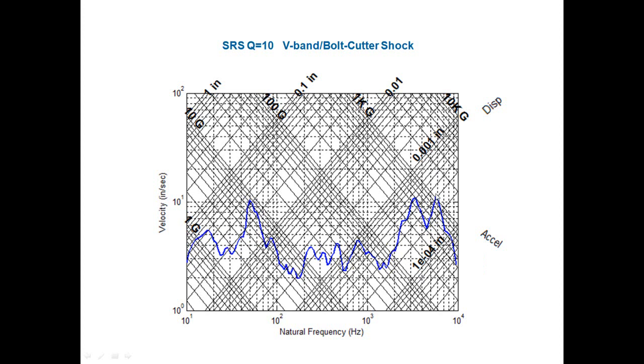If we look at this acceleration time history, it takes about 3 or 4 decades to represent the acceleration SRS. And if we turn our heads 45 degrees counterclockwise, we'll see that it also takes 3 or 4 decades to represent the relative displacement.